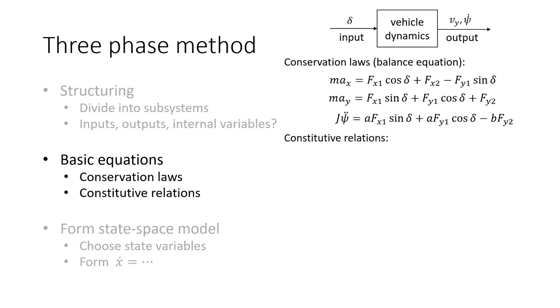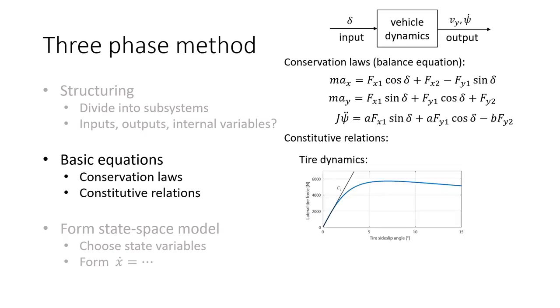The forces Fx and Fy are generated through the tires. As we are mainly dealing with the lateral dynamics, the lateral tire force, Fy, is of importance. The lateral tire force is a nonlinear function of the side slip angle, as visualized in this figure. It should be noted that there are many different approaches to describe this nonlinearity. The most well-known is Pacejka's magic formula.